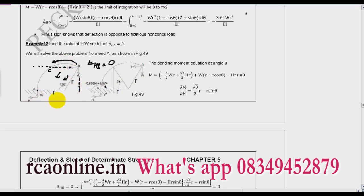And what is that total moment? Total moment is this length into W and H into this length. This is the fixed moment at A. I have calculated it for you and this comes out to be 0.866 HR plus 1.5 WR. So this is the moment, and because this is a fixed support, I will get 1 W here and 1 H here. Now you apply the bending moment equation from this side.